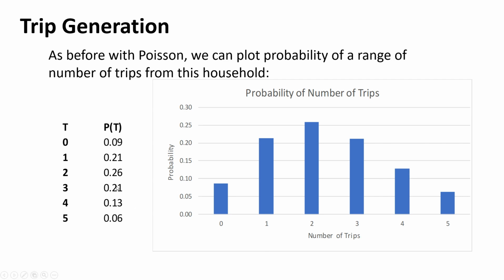I haven't added all these up, but it may be that. If you want a higher confidence level, not just the average value, then if we added up all the households in this one zone, we might expect 100 trips coming out based off the average value, but the 90th percentile value might be 140 trips.